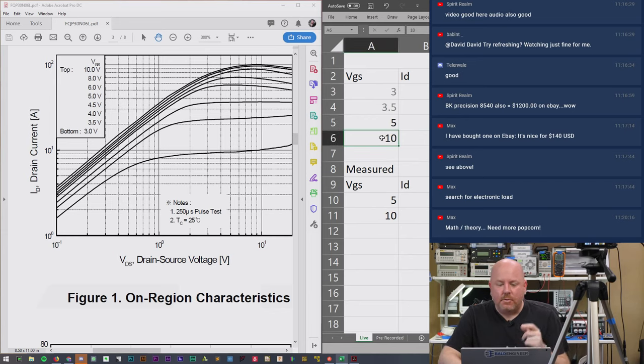And then if you double the VGS to 10 volts, notice what happens to the power dissipation. It drops by like 20-25%. And it's because as we increase the gate voltage, the resistance between drain and source comes down. Make sense? I hope. Not trying to make the math too complicated, but, you know, got to have a little bit of math.